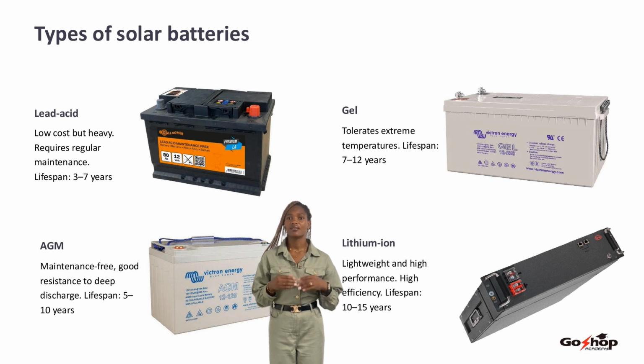AGM battery, absorbent glass mat, maintenance free and resistant to deep discharges. Lifespan 5 to 10 years. Gel battery performs well in extreme temperatures, ideal for harsh environments. Lifespan 7 to 12 years. Lithium ion battery, very light, efficient, and high performing. The most modern technology with excellent efficiency. Lifespan 10 to 15 years.